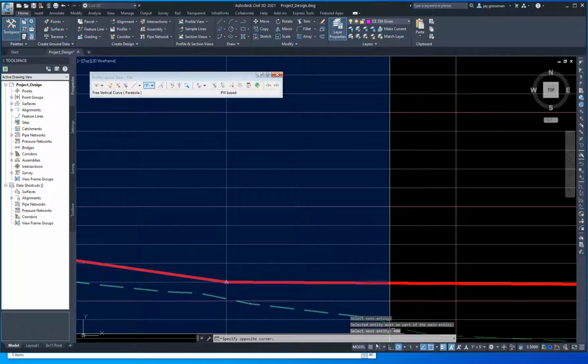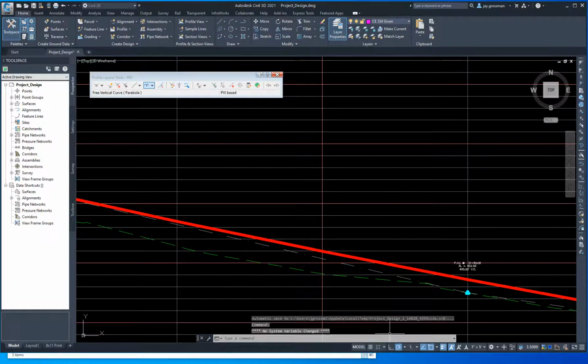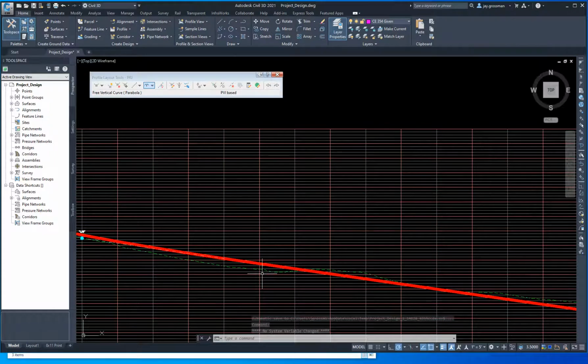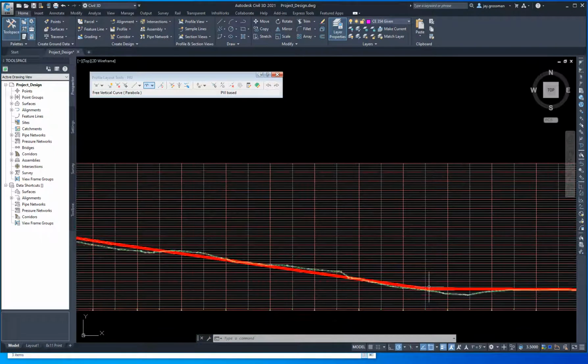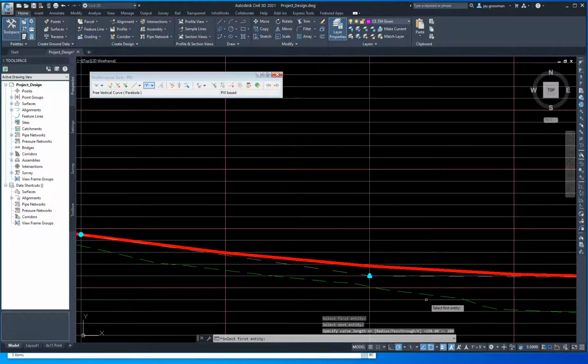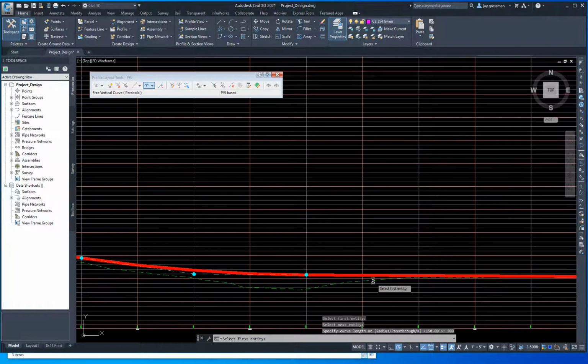And it does not like that. Okay, I hit escape and bounced out of this. I think I did not get a curve in here. I think it failed because I accidentally hit the wrong thing. So I can just come here and hit the curve button again. Entity, next entity, curve length. Let's do a smaller curve. Maybe it didn't like how long my curve was. There it is. Now we got it.